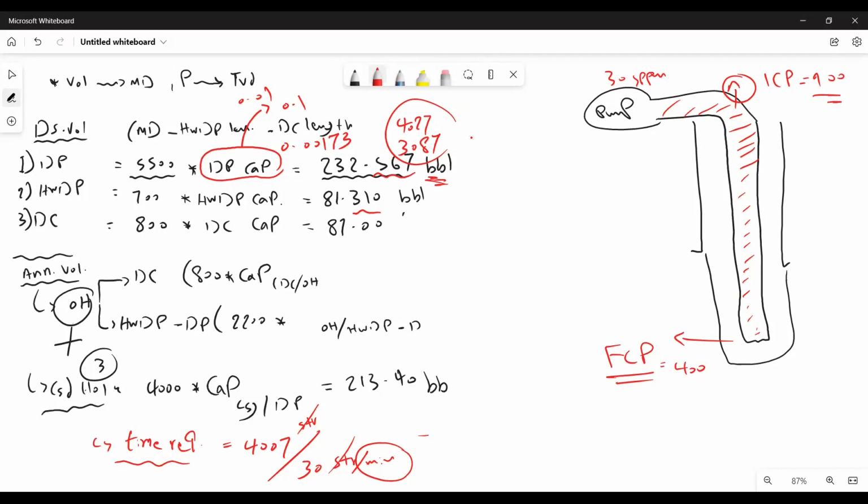So we need to calculate something called the pressure drop. How much is the pressure drop when pumping any number of strokes into the drill pipe? As we pump the whole drill string capacity, the pressure dropped from 900 to 400, so it dropped by 500. If he's asking for any number, let's say the drill string capacity is 800 strokes.